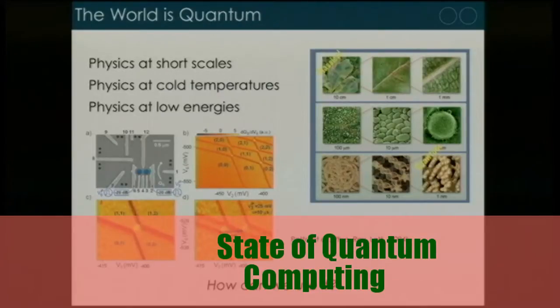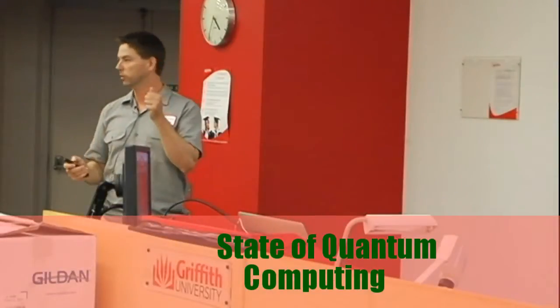Now I won't go into the details, but essentially these gates allow you to deplete electrons from that metal that's underneath them. And you can see I've put these two little blue dots. If you tune the voltages on these metallic electrodes appropriately, you can drive this system so that there can be a single electron localized on this site here or on this site here. And that electron can be controlled, its position can be controlled. You can change the voltage on these two gates so that the electron prefers to sit on one side or prefers to sit on the other side.